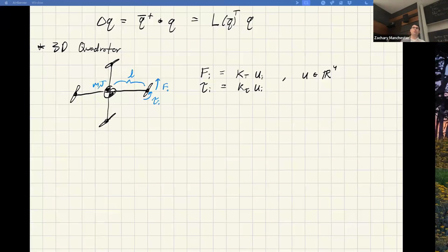these prop coefficients are more generally called aero coefficients, and wings have similar things, right? You have similar lift and drag coefficients. These are basically the propeller version of lift and drag coefficients. If you know anything about that stuff, it's dependent on angle of attack and all these other things. In general, if you wanted to make a really high fidelity model, you'd do either in-the-wild testing or wind tunnel testing, measure these things and tabulate them. A standard thing to do is make a lookup table of these coefficients as a function of speed, Reynolds number, whatever, and then interpolate into the lookup table in your model, so that you can make these semi-empirical aerodynamic models with just tables of these coefficients that you can fit empirically.